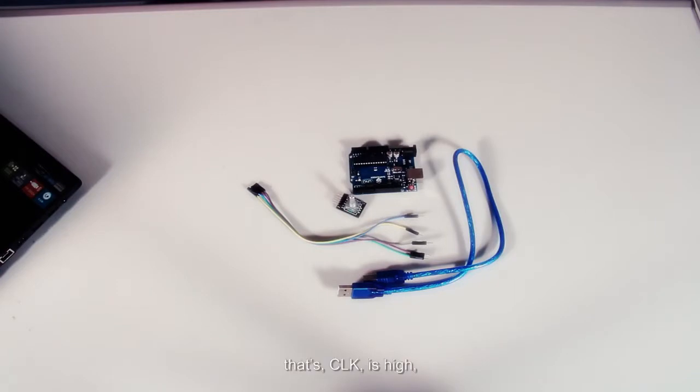When channel A (CLK) is high, if channel B (DT) is high, the switch rotates clockwise. If channel B is low, the switch definitely rotates counterclockwise. As a result, if channel A is high, you can judge whether the rotary encoder turns left or right as long as you know the state of channel B. That's all for the principle.